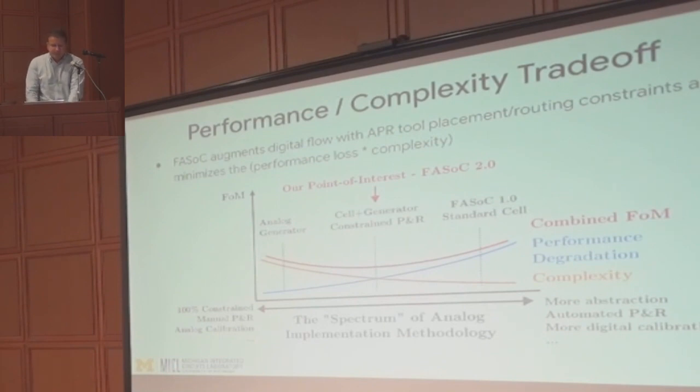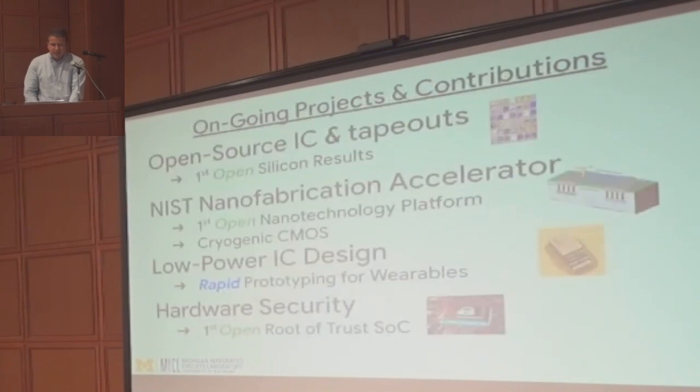We're trying to avoid taking in all the PDK DRC rules that come with full custom automated layout, like routing or active layer drawing. That gets really complicated as we go into advanced nodes like FinFET and so on. Also, with the rule of diminishing returns, the time required to port to a new PDK or even a new design topology would essentially make an automated full custom analog generator too costly to make across PDKs and cases. And we've seen that with some of the generators out there.